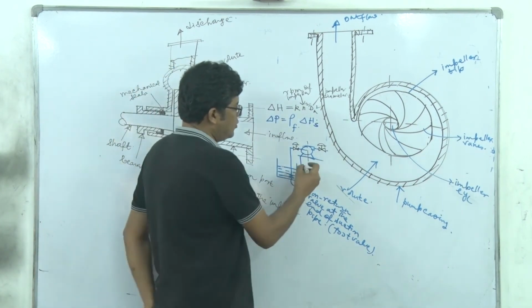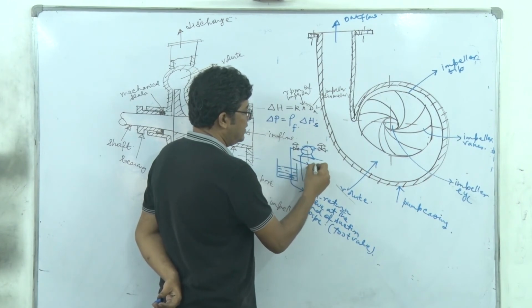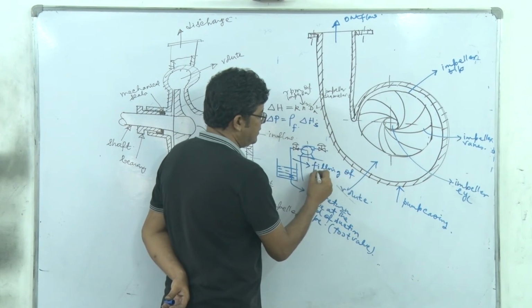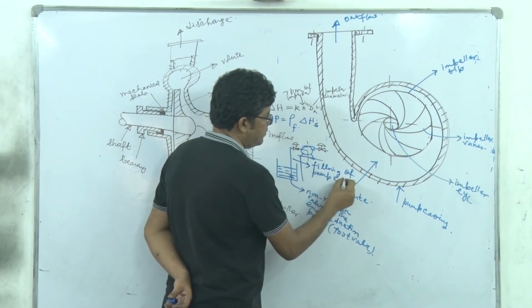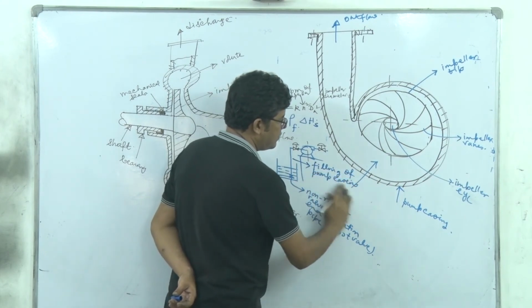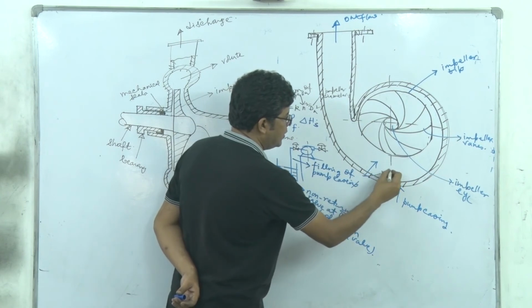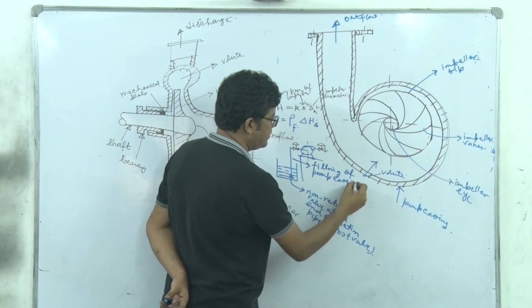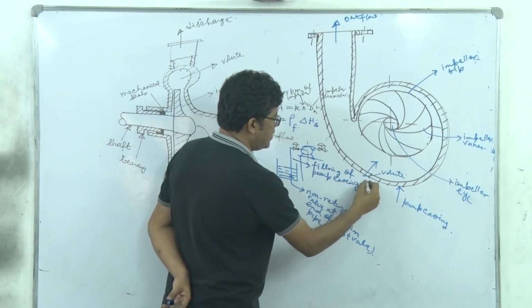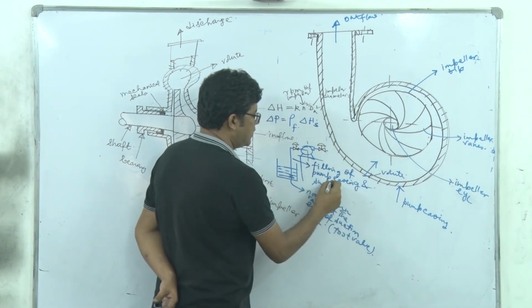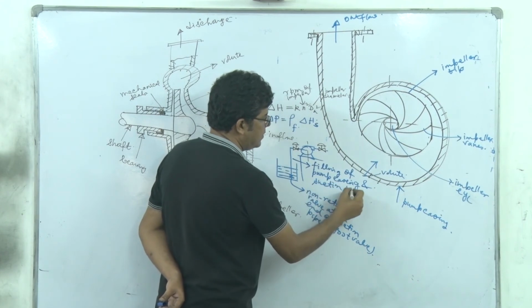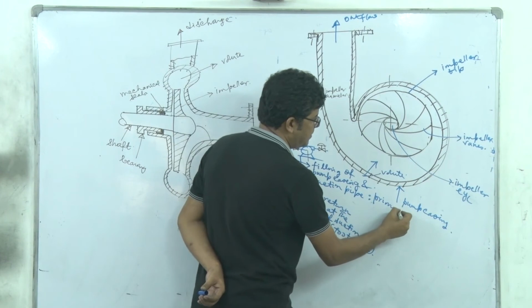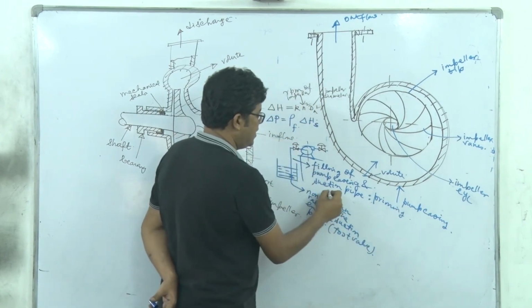So we have to note here that filling of the pump casing and suction pipe, this operation is called priming of the pump, right?